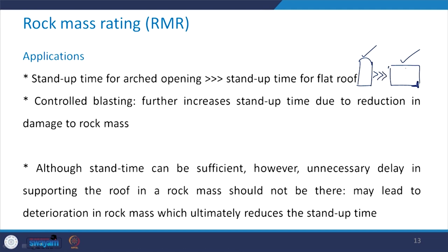Now, if for the excavation purpose you are going for controlled blasting, that further enhances the stand up time, because when we go for controlled blasting, there is a reduction in the damage to the rock mass and therefore the stand up time increases. You have seen that stand up time can be as large as 20 years for a 15 meter span of the tunnel in case of a very good quality rock mass.